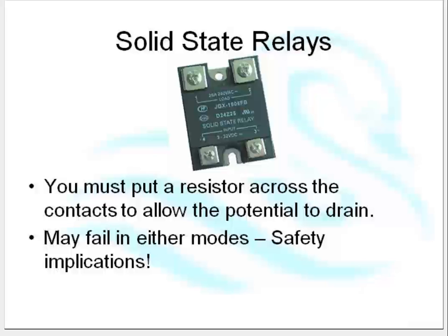Has any of you seen solid-state relays before, or installed solid-state relays? Well, a couple of things you must know about solid-state relays. Firstly, a solid-state relay can fail in either mode. What that means is it can fail on. 50% of the time they fail on. Now, if we're outputting to something like a heater, you don't want a heater to come on permanently. So there are particular rules that apply to solid-state relays, and we have to be careful with the safety of them. The second thing about a solid-state relay is it's a high impedance device. It will switch on if you have anything between 3 volts and 32 volts.